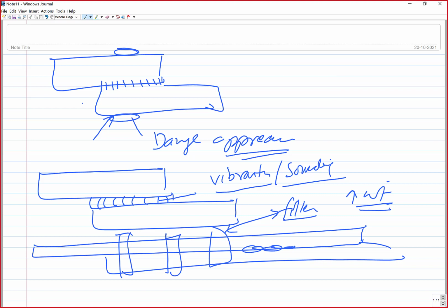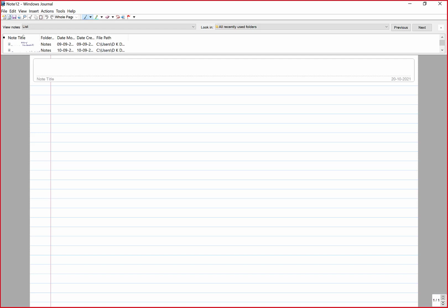So as compared to the riveted joints and those consumable welding joints, adhesive joining contributes less to the weight gain. So indirectly, you can say the weight saving is another important feature, especially in the automotive industry, where if possible, you can avoid the rivets, or it can be used in combination with the rivets if very high reliability is critical for the performance.